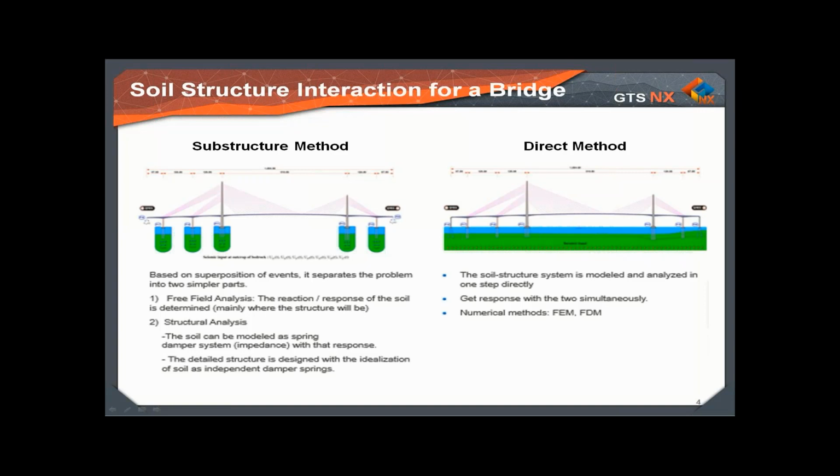In this method, the structure can be modeled in a simplified way, but then it is necessary to remodel the structure more precisely in a second stage, where the result of the motion is applied at the base of the structure in order to determine the detailed response. Therefore, the programs used for this analysis must be compatible.